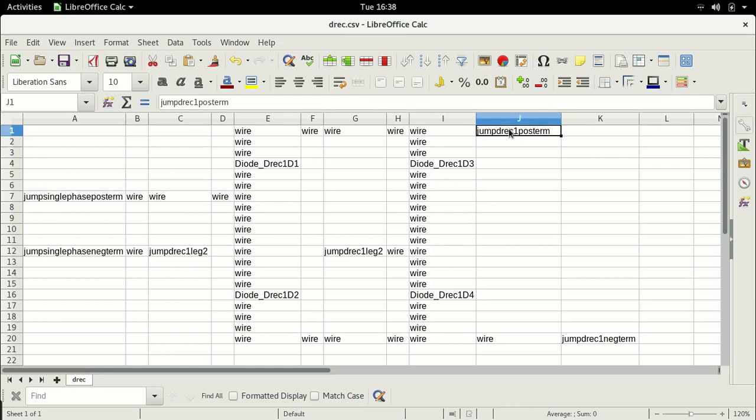Alright? This is a clear connection. Here, this is a branch. This is a branch that is starting from this node, and you are connecting this branch segment to another part. That's okay. But if you put this jump label right here at the node, you are extending the node, and that is ambiguous and the circuit will not work. You cannot do this. You must always have at least one wire element or any other element next to a node. I would say when you have a node, always put a wire element next to it.